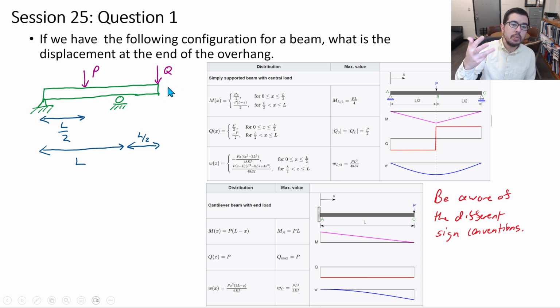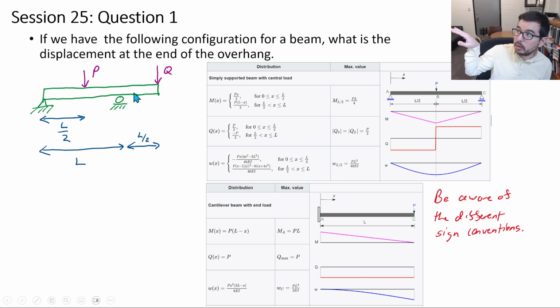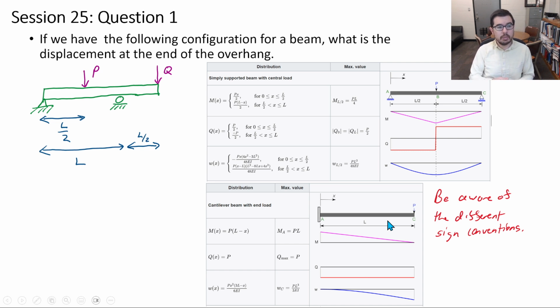So essentially, it's a superposition with three things. It's got this portion here to tell you what the slope is there. Then it's got a rigid approximation of that slope for how high it would get, and then it has how much that region is going to droop over as a cantilever. All right, so it's a problem that you get to approach,